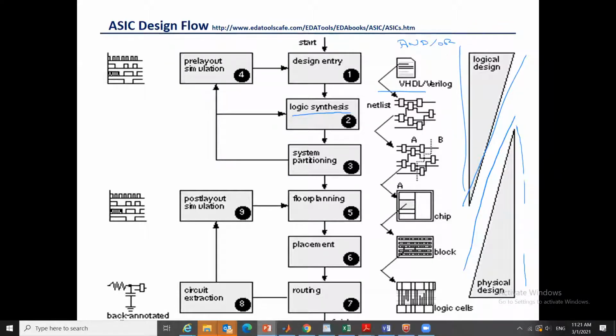The netlist then gets subjected to system partitioning, meaning we want to know how to best define our system, and there are tools that do this in the ASIC design flow. Then there is what we call technology mapping, which is not shown here. It means he is going to say, well, I have those gates, I'm going to map them to this technology, this type of gates and so on. And there are simulations that happen. You see all this flow where we optimize things and go back through this loop. We now do technology mapping and optimization. I want to size my gates, make them smaller, etc., to satisfy power and timing conditions.